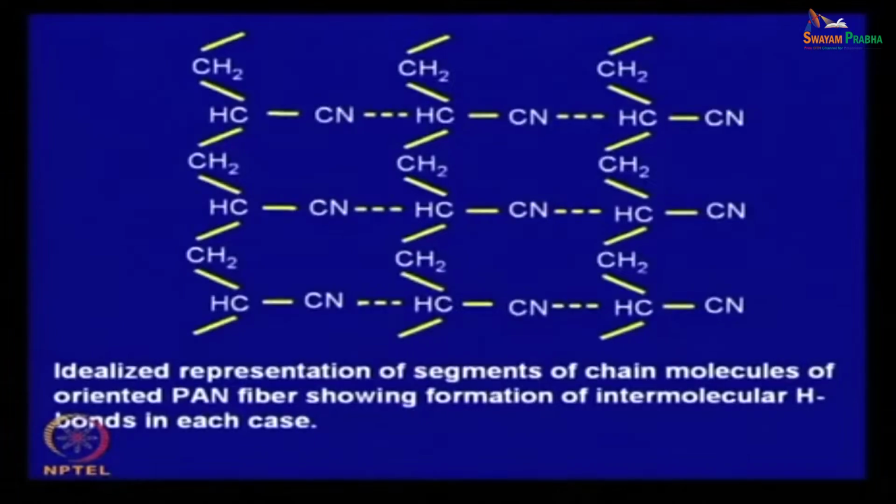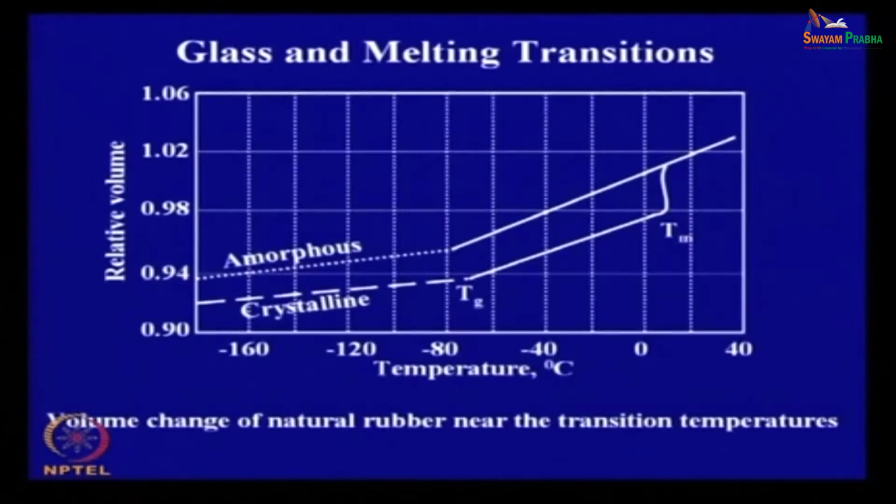So, in case of nylon, in case of cellulose, in case of polyacrylonitrile, that means a polymer, if it contains some polar atoms like oxygen, nitrogen, fluorine, chlorine, halogens, etc. So, that enter into hydrogen bonding and that influences the properties. So, you go through these structures and for new polymers, new other unknown polymers, whether there is hydrogen bonding or not, you can judge yourself looking at the structure.